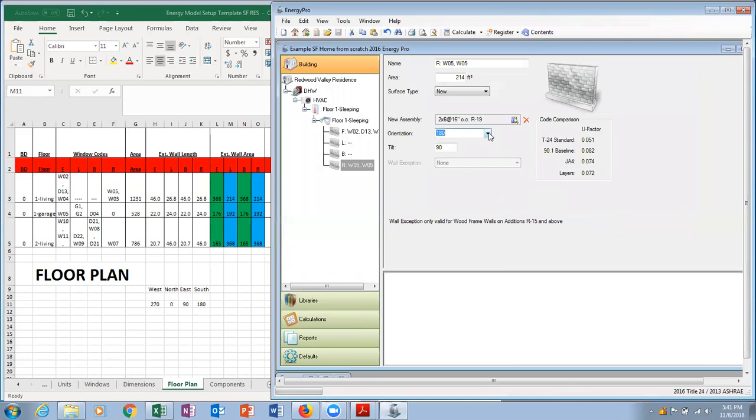I think if it's within 20 degrees of true north, south, east, or west, you could assume that it's that main direction. But it's always better to use the exact orientation. So let's say 77 degrees was the front orientation. Just add 90 until you get to a full circle, and then just make the calculation add up. Great, thank you. And if you wanted to do it without the degrees of a circle, you could definitely use the preset northeast, southeast, whatever.